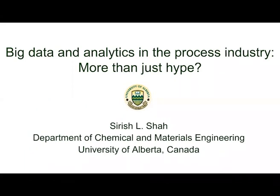All right, another question. How can process engineers with 2 to 3 years experience develop their knowledge in process data analytics? I suggest learn to work with simple machine learning techniques. Regression, least squares regression is a very simple machine learning technique, you can call it. Start with that, curve fitting and so on, polynomial curve fitting. Start with these ideas. Obtain simple models of your process. Simple models of your pump, for example, would be a good way to do things.